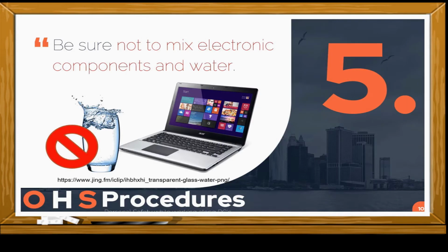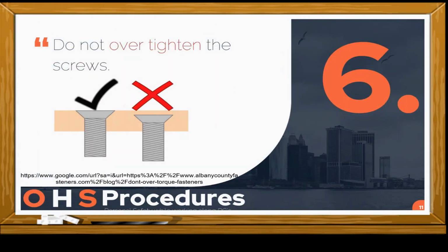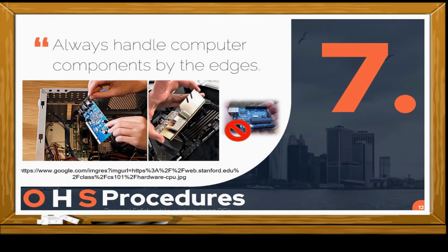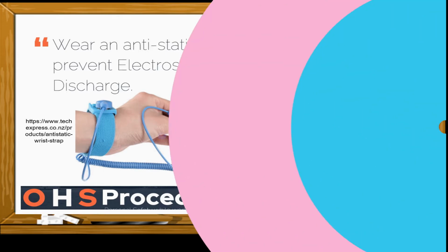Number 5. Be sure not to mix electronic components and water. Number 6. Do not over-tighten the screws. Number 7. Always handle computer components by the edges. And last but not the least, number 8, wear an anti-static device to prevent electrostatic discharge.